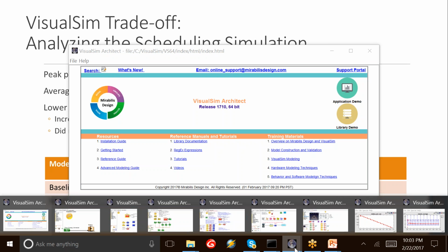So in this one, for example, I've got 2 workload generators that are fed to 1 and 2. And here I've got a whole network defined in these 2 processes. I've got an initial routing table based on my connectivity here, the distances and the speed. I've also got some logic here where dynamically I remove a link and after some time I add a link. So I remove the link at 100 and I add the link back at 150. Let's run the simulation and see what happens to the system.